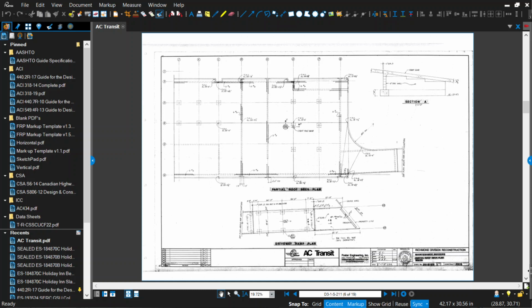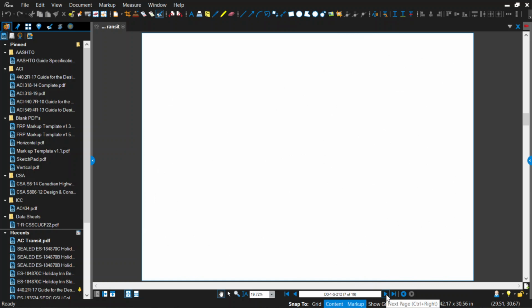Dangerous. Right. But so for a slab like this, we might have an engineer give us the maximum positive moment here and the maximum negative moment here, positive moment here. So for our analysis, these would all be different cases, and we could get the depth of the tendon from here.